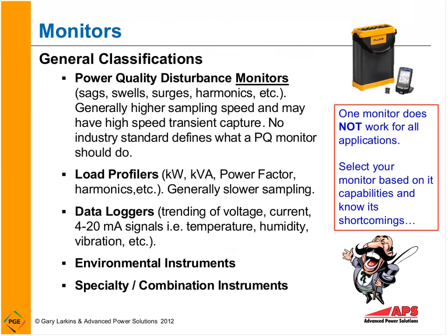Power quality monitors. Now notice I have it underlined up here, power quality disturbance monitors. A lot of companies call these power quality disturbance analyzers. The monitor does not analyze the data, you do. The monitor gathers the data and presents it. So it's very important you understand how your monitor gathers data, what its capabilities are.